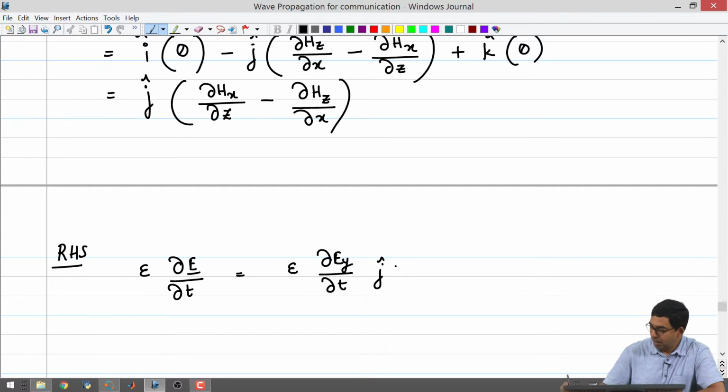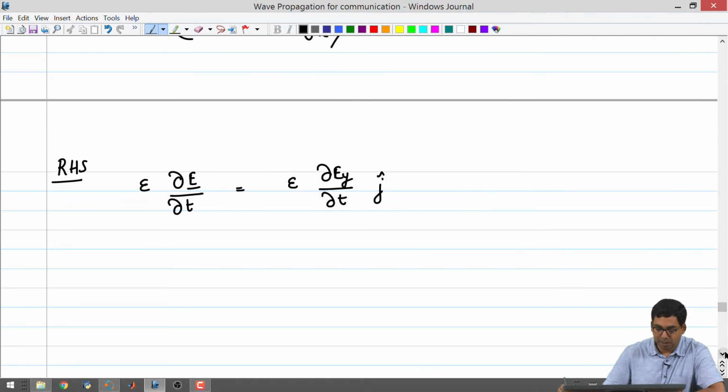Having expanded this, we are going to start writing down the finite difference form, identifying the unknown and bringing it to the left hand side. Here we have a quantity with a time derivative, so the unknown for this equation is the value of that variable at the next instant of time. So you have to use forward difference for time.